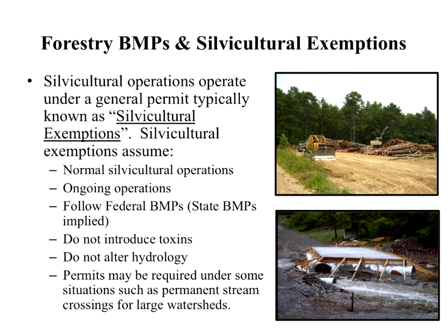Now, there's also another term that we need to discuss, and that is silvicultural exemptions. Silvicultural exemptions really aren't truly exemptions. Silvicultural exemptions really are a blanket permit. They're a general permit. Basically, silvicultural exemptions mean that we do not have to get a permit when we're dealing with, particularly around forested wetlands, around streams, these types of things. We don't have to get a permit, as long as we follow certain conditions.